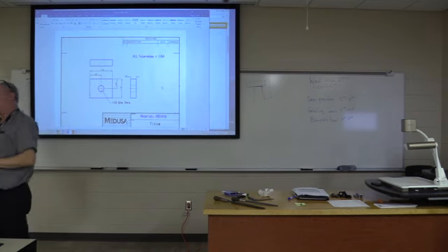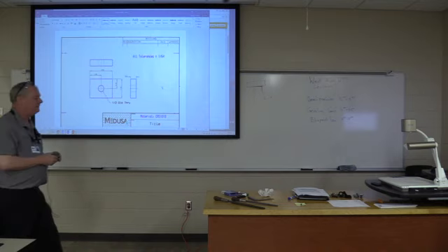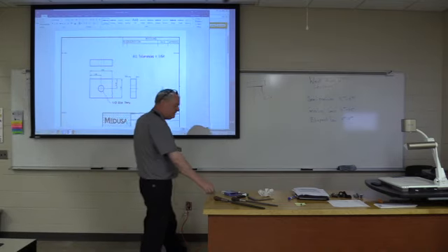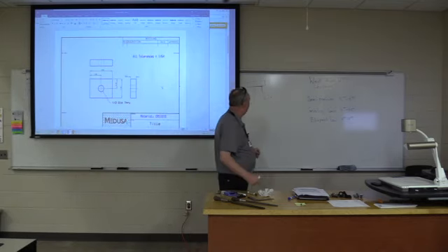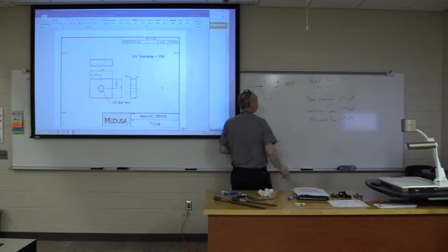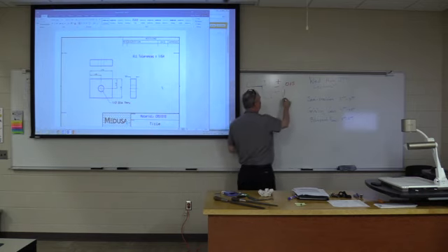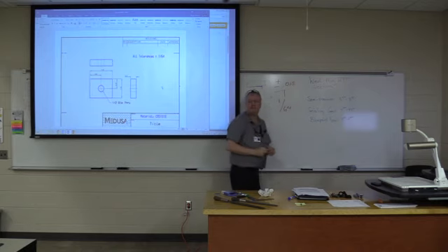So there's tolerance in there. And generally, we're in semi-precision machining. Semi-precision implies a tolerance of plus or minus 0.015 of an inch. That happens to be the decimal equivalent of 1/64th of an inch.